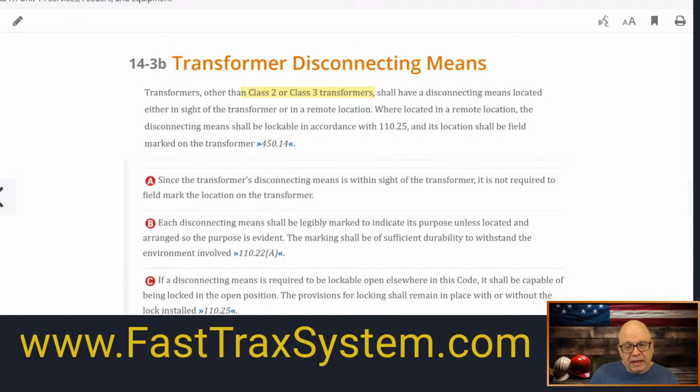And then typically that's going to be like a 120 volt circuit, or since it's more of a power circuit than what we would get on the secondary side of these little transformers, these class 2 transformers, for example, which is going to limit it. And so you really wouldn't put any protection on that. And you all are familiar with that. You go right to the doorbell. You don't need to have anything on that. Now,